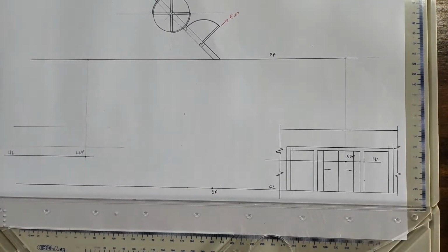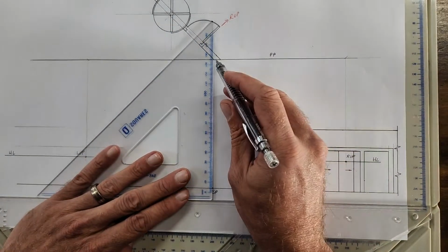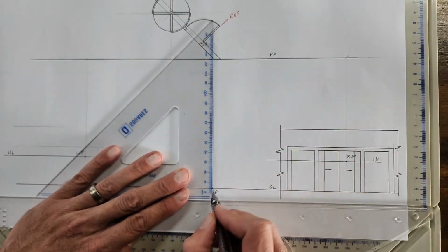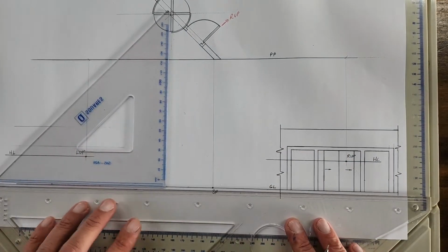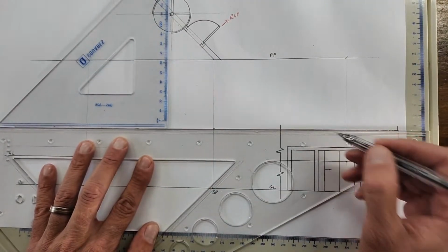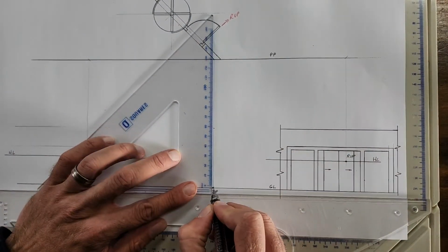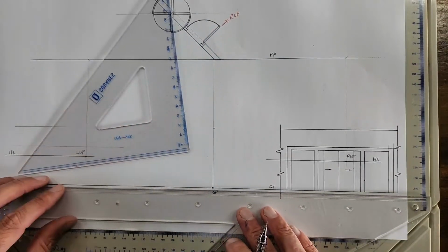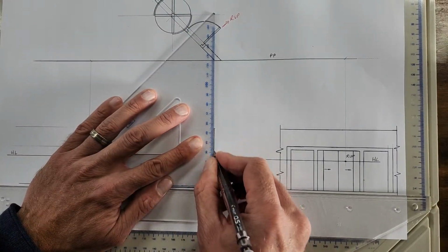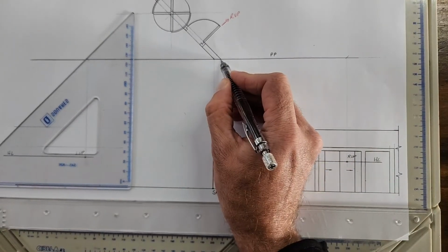So when I start myself off, I'm going to start from the top view, project this line, it's in line with the SP. Alright? This line is touching the picture plane. So on this standing point, it's going to be the same height that I get from my elevation. Okay? So this height here, this corner. So I just want to line up this page. There we go. Alright, that's a solid line. So you can see here, it's really simplified. From this point, which is this point here, it continues to the right hand side.